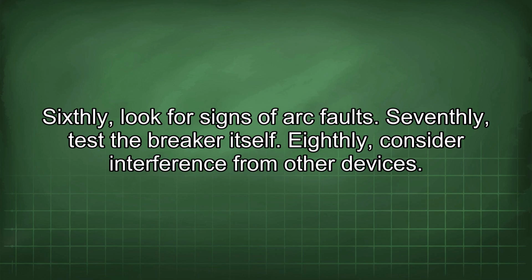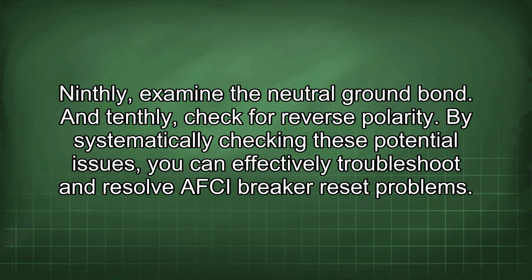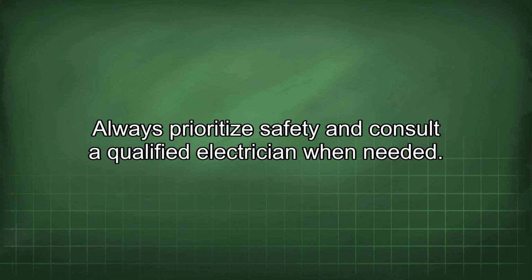Seventhly, test the breaker itself. Eighthly, consider interference from other devices. Ninthly, examine the neutral ground bond. And tenthly, check for reverse polarity. By systematically checking these potential issues, you can effectively troubleshoot and resolve AFCI breaker reset problems. Always prioritize safety and consult a qualified electrician when needed.